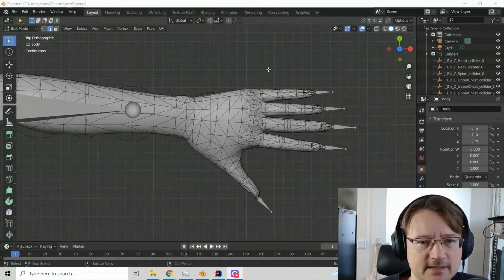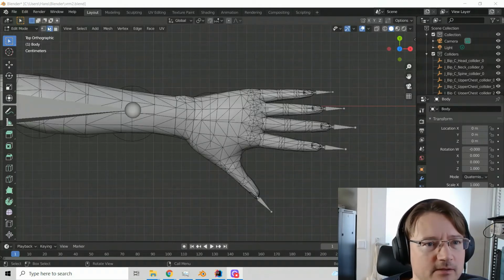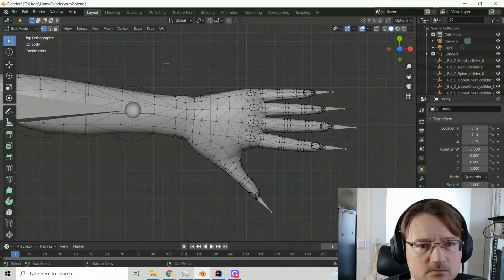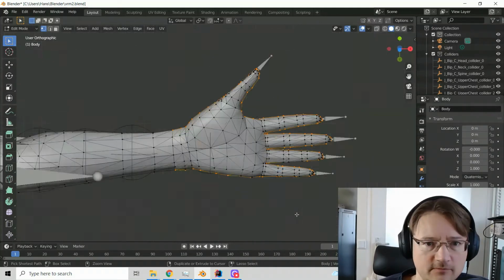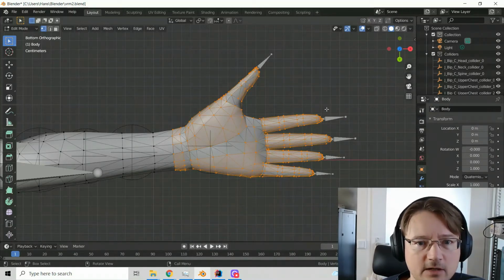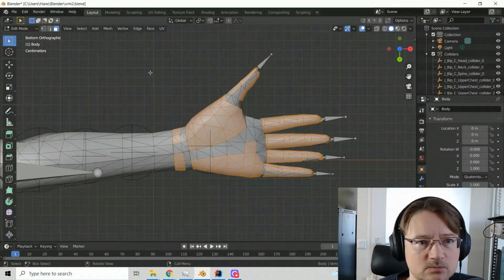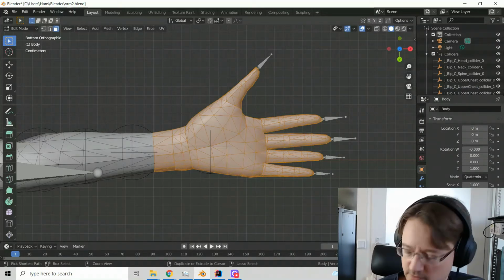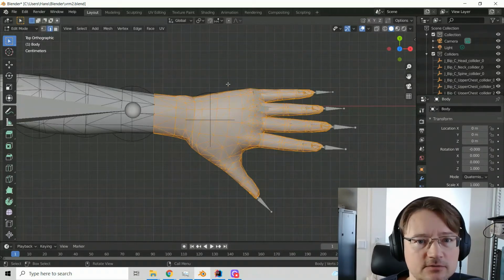Let's try to select the hand vertices and faces and edges. So I will make first a vertices selection over here, and then I will switch the view to the bottom view and also select that part with shift. Okay, and then I also see I need to select faces over here. Yes, and switch back again. Right, the edge faces.